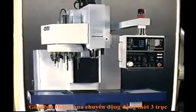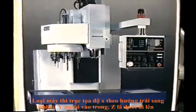Thread milling would be the ability to do 3 motions at the same time. Now on this type of machine, sideways is always called the X direction, in and out is always called the Y direction, and up and down is always called the Z direction.